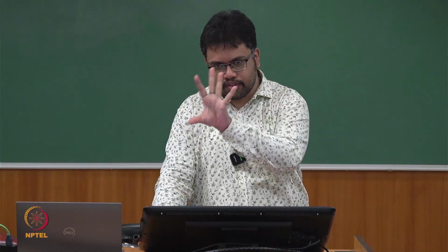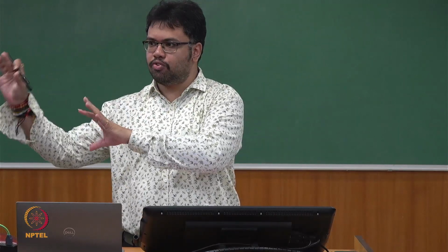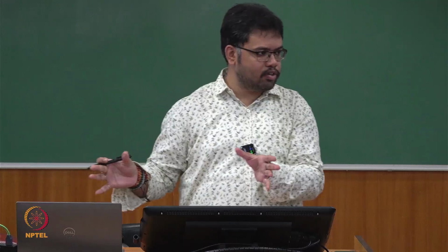You cannot solve it directly: you have u1 double dot plus u1 into something plus u2 plus u3 plus u4, u5, all those things start coming into the picture, so you cannot write it directly. But think, in the single degree of freedom system our life was very simple: we have m u double dot plus k into u equal to something.